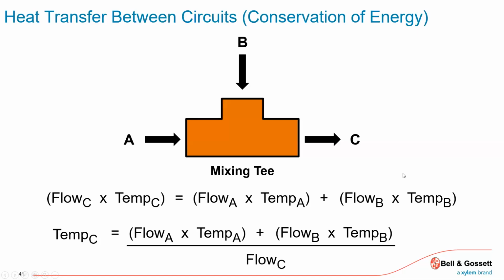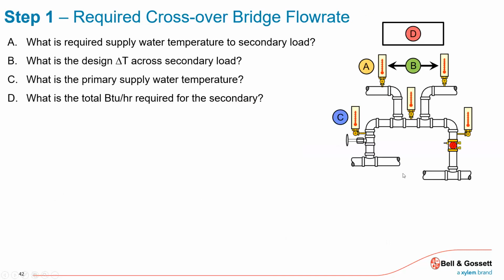So you can use it for temperature control. And it gets into a little bit of math, but all it's saying is it's like a mixing valve, right? I mean, that's what it is. So I got some hot, I got some mix, some cool, return, whatever. If I was doing a shower head, perhaps, I got some hot coming out of the water heater. I got some cold blending at that mixing, and I got a mixed feed. I'm doing the same thing on these individual circuits.